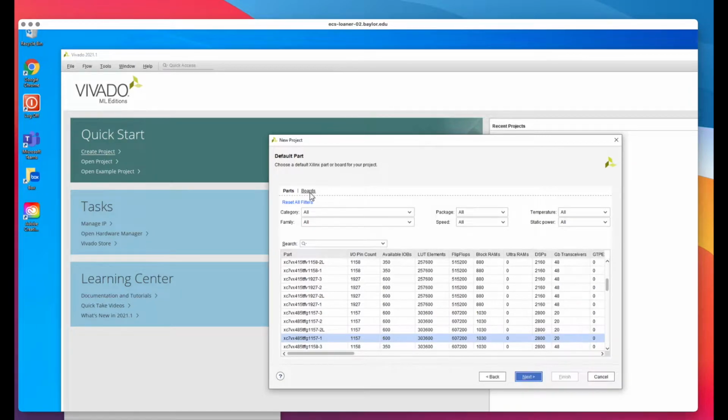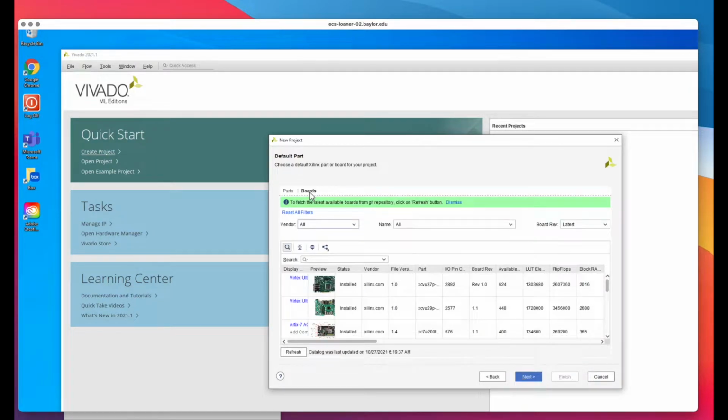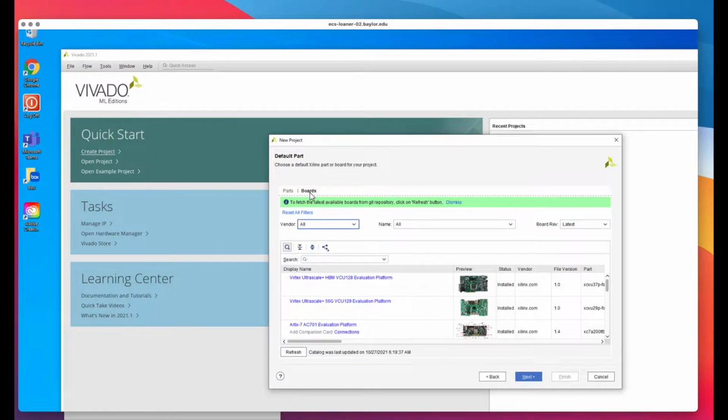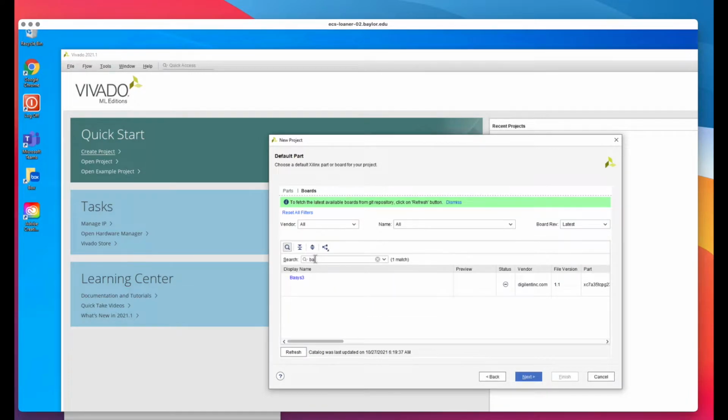Okay, next it's important to remember the target board, especially if you're going to connect the Basys board to your computer so that you can program it. Sometimes we're just doing a simulation and we don't need to worry about the board. We're not going to use the target, but in this case, that's the whole point. We want to do something quick and easy and get an early victory. All right, so we need to specify the target. It's Basys, B-A-S-Y-S. It's good to know how to spell this so that you can do a search.